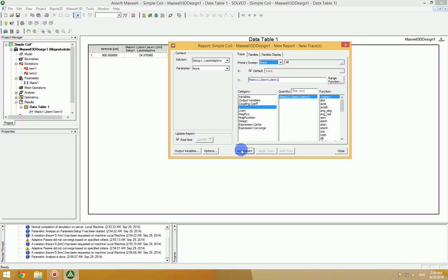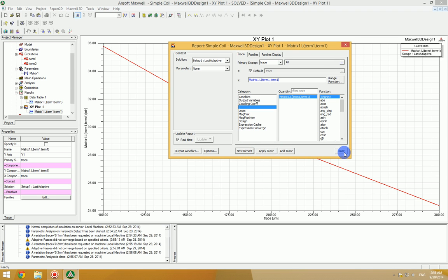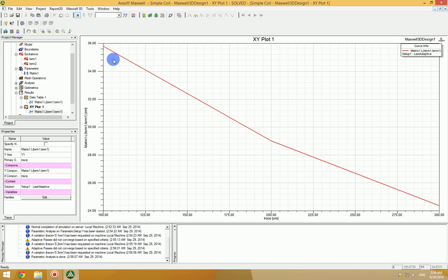Because I have just 3 points here, it's not going to be a very smooth plot, but it's going to be informative enough. So now you can see that the value of the inductance is dropping when you increase the trace width. One reason for that is because when you increase the width, you are basically decreasing the active area in the middle of the inductor, and that will cause less flux in the middle, and therefore less dΦ/dt, and basically less inductance.